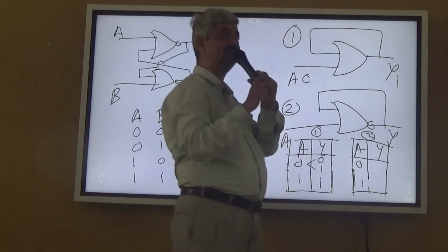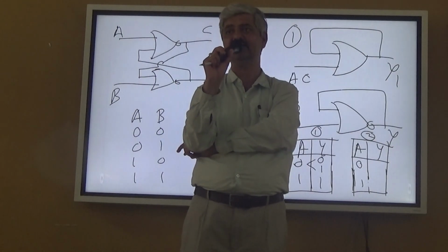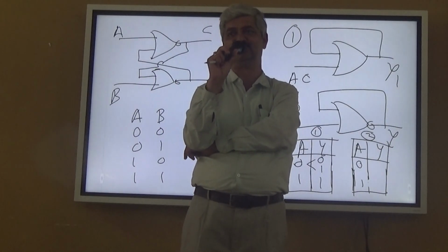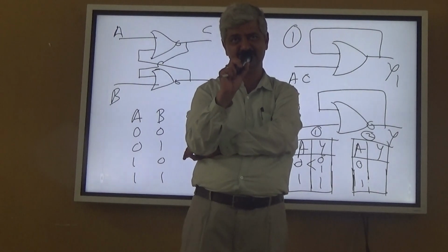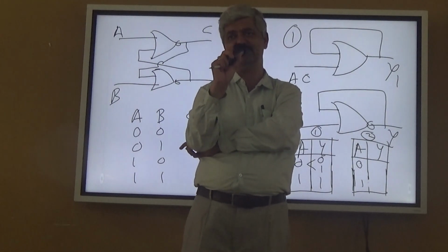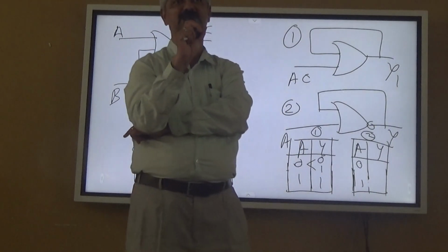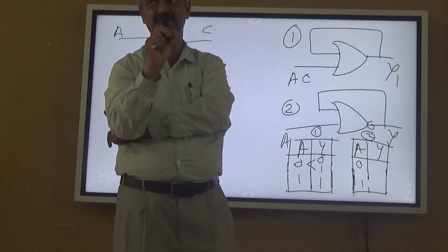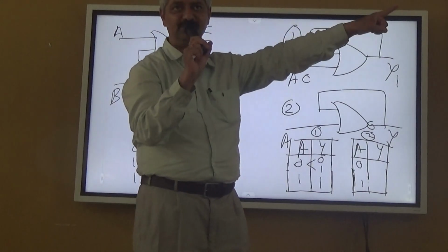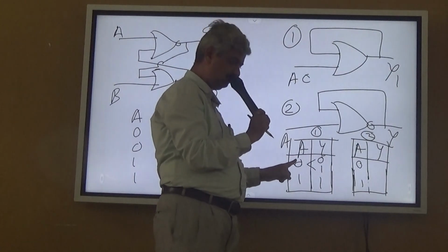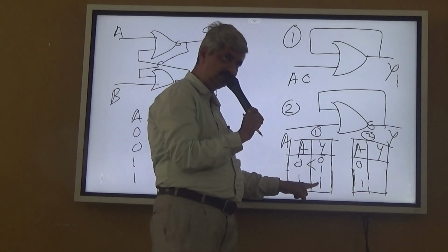This is a circuit with feedback. A circuit without feedback will always have one-to-one correspondence or many-to-one correspondence. Many input combinations will result in one output combination, or every input combination will result in a unique output combination. But in any case, one input combination will not have multiple output combinations. For a combinational circuit, a given input condition always leads to the same output. Whereas here, with input 0, the output can be 0 or 1. But if input is 1, output is 1.